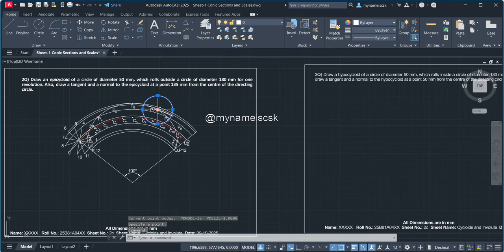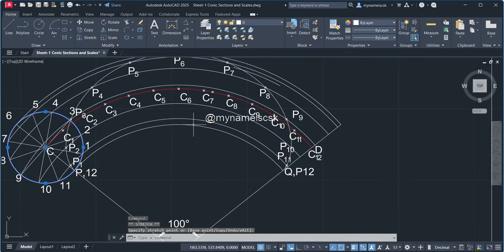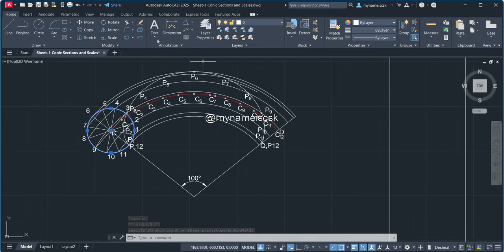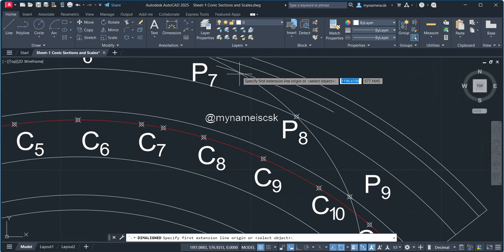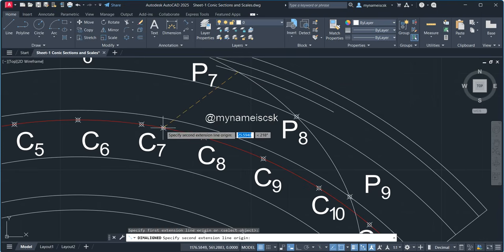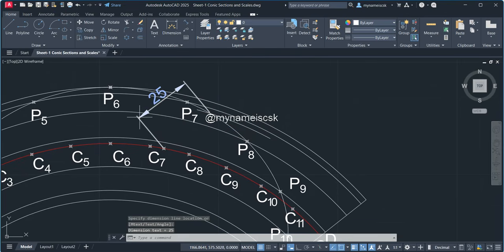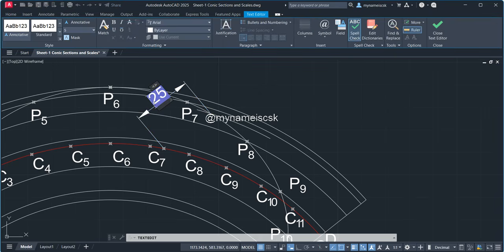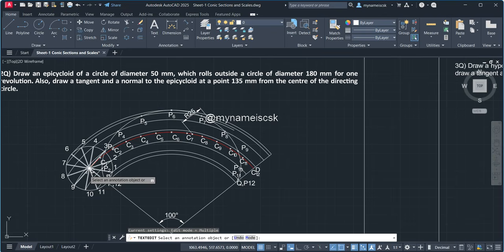So again move back your circle to the same center. Okay, so it is cutting somewhere here. This radius is 15. So from here you have to take the align dimension, and you have to show that it is at a distance of the radius of that one. Okay, if you click here you will get align 21, align 25. Escape, double click and rename it as R25 and come down command. So this distance we have taken as radius 25 because here our circle diameter is 50.